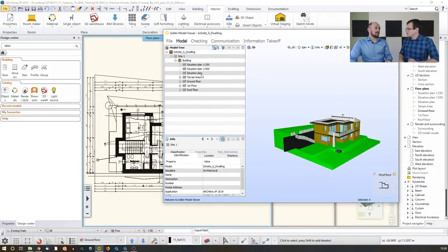And in practice, it usually happens that you pass on the building in one format, and in several other formats, you pass on the drawing itself. If there is a highly detailed final version of the 2D details and anything else, then you can use both. But if you would like to pass on the building itself, if you would like to export the building and make the other person be able to edit the walls as walls and the columns as columns, you will use the IFC file.